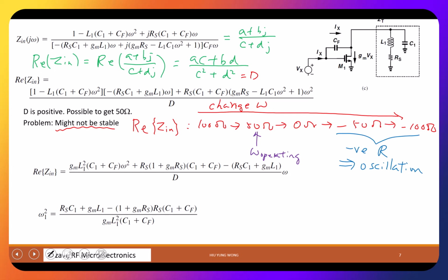Your noise power spectral density is a white noise, right? You have those low frequencies. They are small, yes, but now when you talk about oscillation, it means the gain is theoretically infinity. So they will just keep amplifying and screw up the whole circuit.